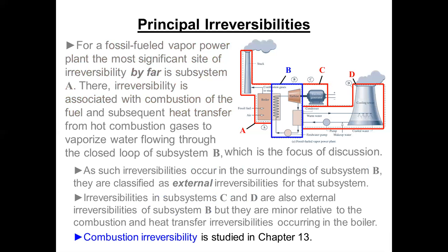boiler. And we're not going to say much at all really about combustion irreversibility, but think about if it was a reversible process. That would say you could take the products of combustion and run it backward and produce the individual components. The combustion air and the natural gas or methane, whatever, we would, I guess, put heat into the system and the reaction would go in reverse. And we know that's probably not going to happen, which means that it's highly irreversible.